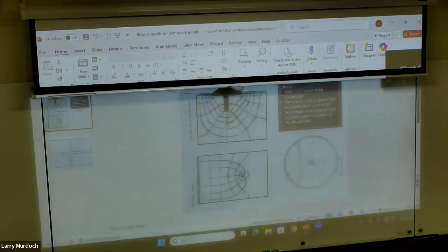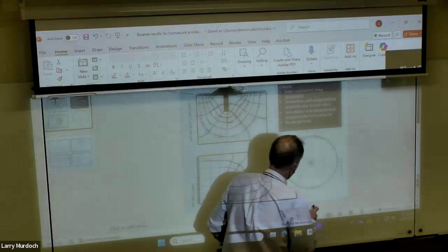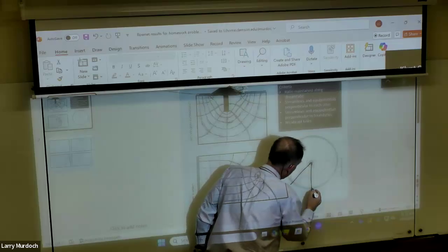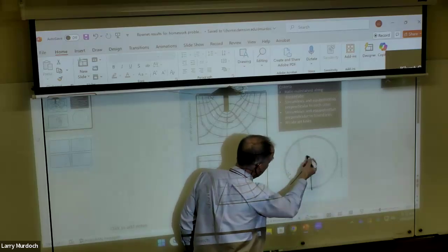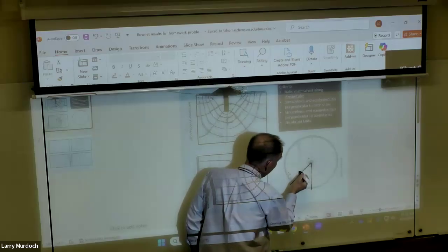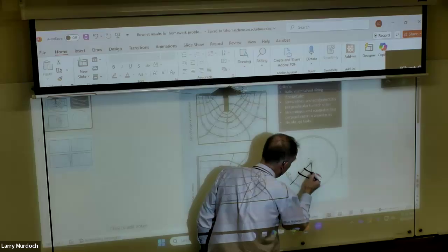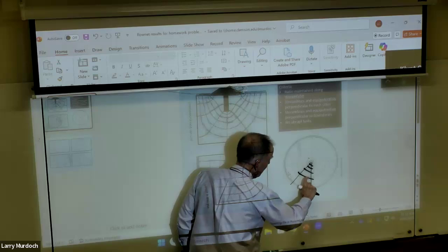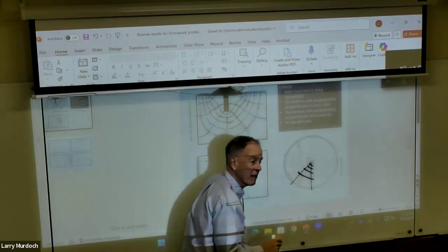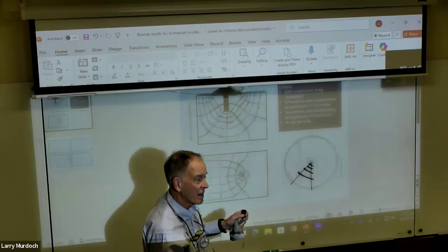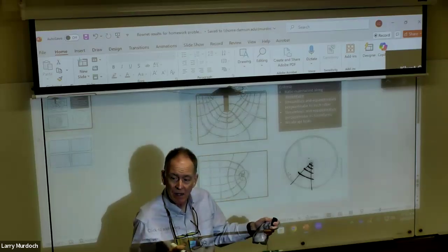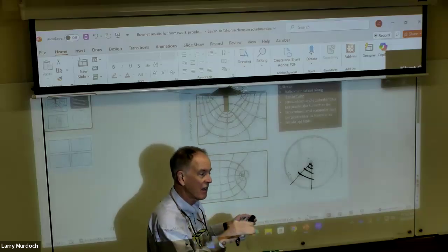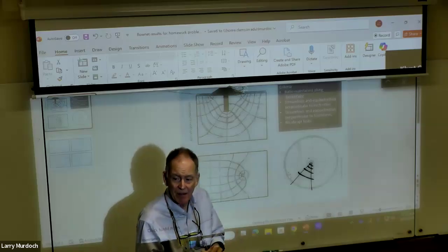For this problem here, this was probably the one that was missed the most. What is important to show on this one is equipotentials are streamlined like that, and then the spacing between the equipotentials is decreasing. A lot of people felt like the spacing should be even. And if that's the case, then the gradient in the hydraulic head is the same everywhere.